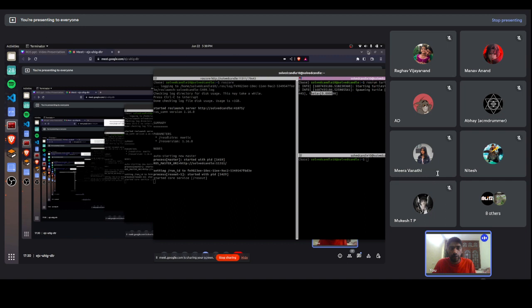So now what I'm going to do is I'm going to run another node. What I'm going to run is called turtle_teleop_key. So I'll just write it down: rosrun turtlesim, again rosrun, name of the package, and then I'm going to run a node which is called turtle_teleop_key. Okay, so it says reading from keyboard.